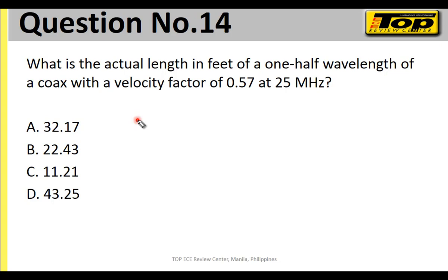What is the actual length in feet? In feet, we're talking about feet. Okay? Not in meters, but in feet. Of 1/2 wavelength of a coax with a velocity factor of 0.57 at 25 megahertz. The operating frequency is 25 megahertz. How do we compute for the wavelength in feet? That will be wavelength is equal to